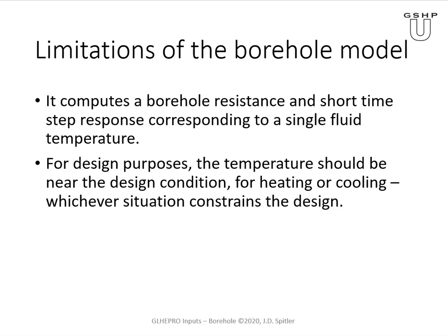Okay, limitations of the borehole model. The main thing that comes to mind is that the convective resistance inside the pipe, or if you have groundwater-filled boreholes, the convective resistance outside the pipe, correspond to a single fluid temperature, or with the groundwater-filled boreholes, also a sort of single operating condition.